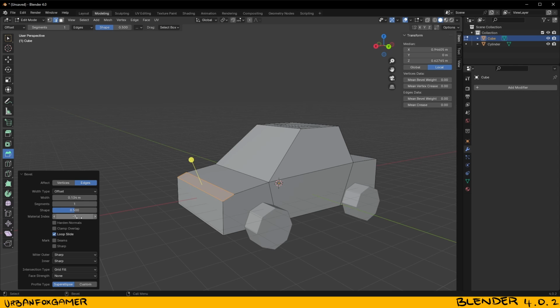You can add segments here. As you can see, this bevel is the chamfer or the fillet, but I know those three are three different things, but they generally have the same concept of adding curvature to an edge. So you can affect the vertex or the edge. There are different types. There's the width, the segments, and the shape, yada yada yada. So if you're happy with the results, let's just say I just wanted to add two segments and click here.